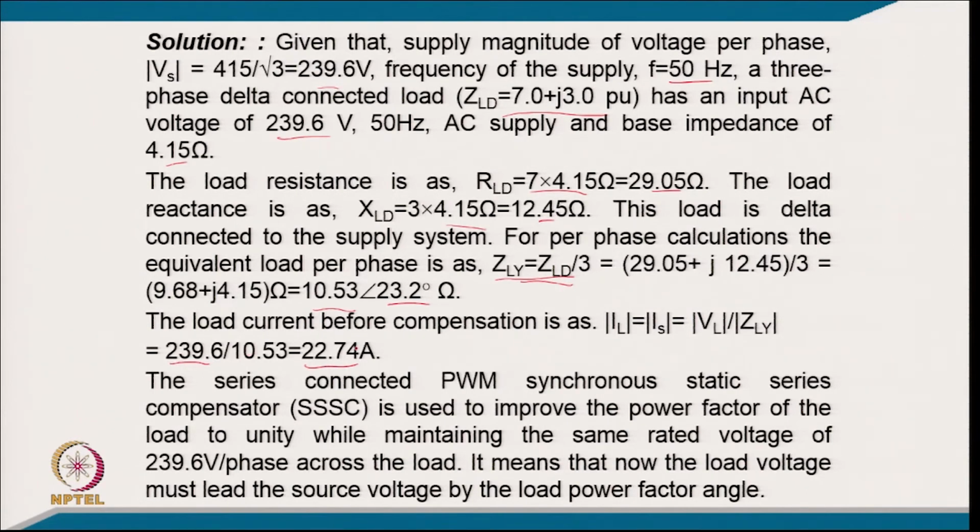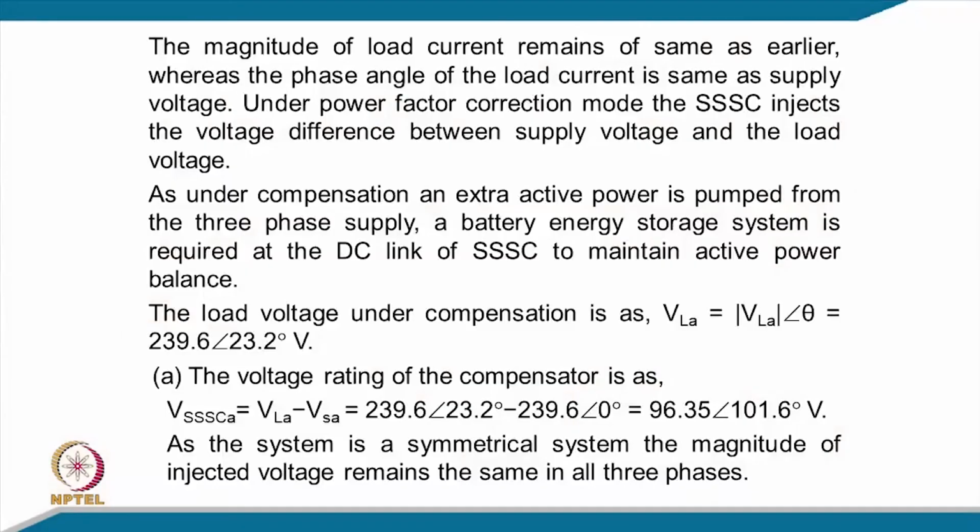So, it comes 22.74 ampere, and the series connected static synchronous compensator is used to improve the power factor of the load to unity while maintaining the same rated voltage of 239.6 volt per phase across the load. It means that now the load voltage must lead the source voltage by the compensator by the load power factor angle.